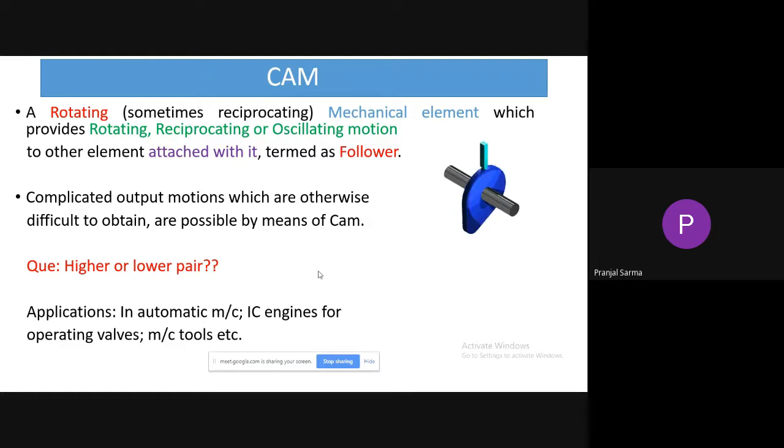After that, the operating of the exhaust will come. So in the exhaust stroke, ideally the exhaust valve should open, and for some time throughout the exhaust stroke it should remain open. So the requirement of the motion is something like that for a certain time. This intake valve should open, remain open for some amount of time, and after that it should close and remain closed for a certain particular duration of time, so that both the strokes could complete within that time. After that, the exhaust valve should open, and it should remain open for a certain amount of time.